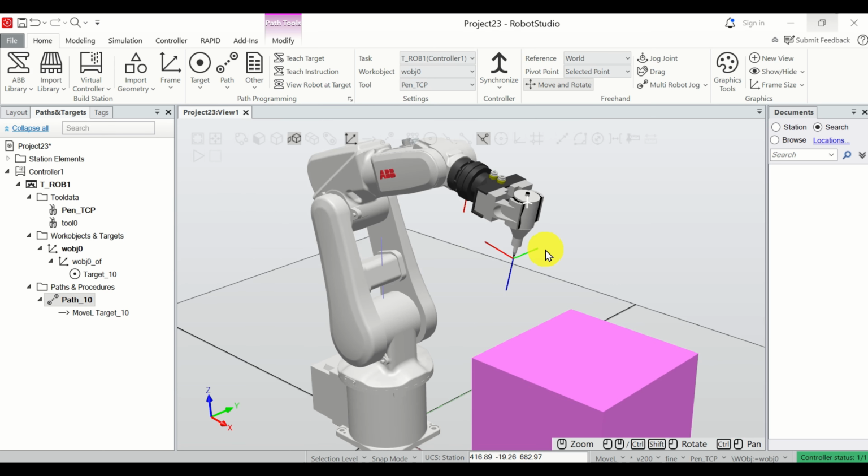However, this will take me maybe 10 minutes to define such a work object coordinate system, and in the interest of time, I will do it manually. That is, I will manually move my robot by using snap tools, and then I will memorize the points.